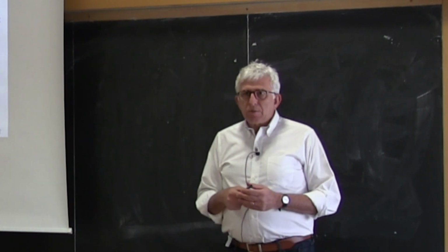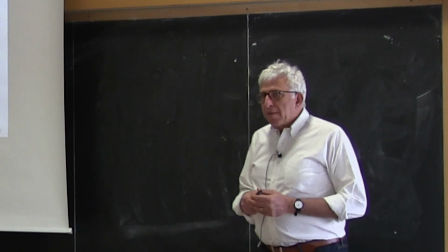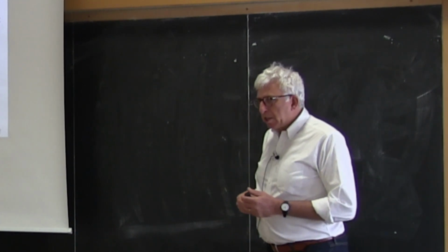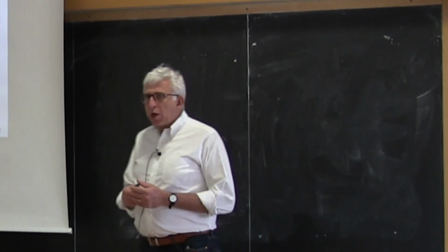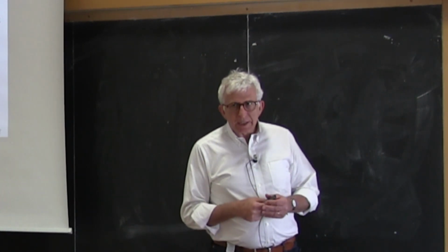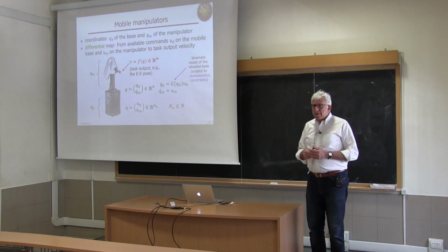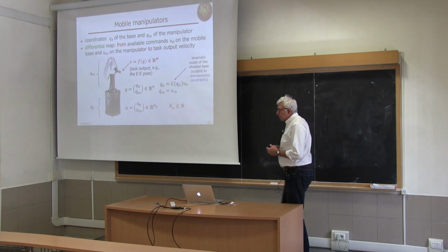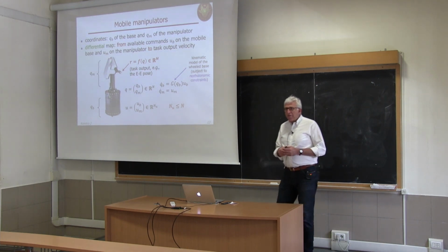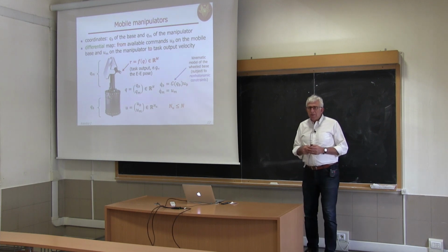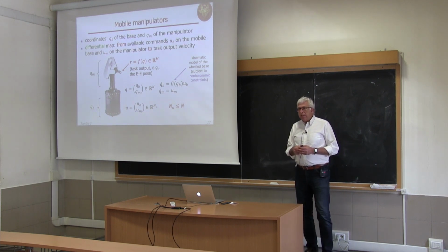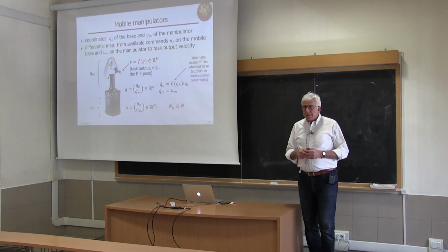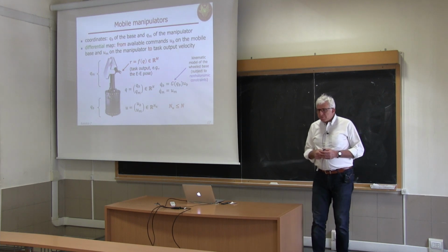The second extension that we have just seen is moving from a pure planning stage to a control stage in which we use feedback in order to recover possible errors in the execution of the task. We have seen that a simple proportional term to the error added to the desired task velocity is enough when dealing with velocity inputs, and a PD scheme is the one that is needed in order to recover the error when we are dealing with acceleration commands.